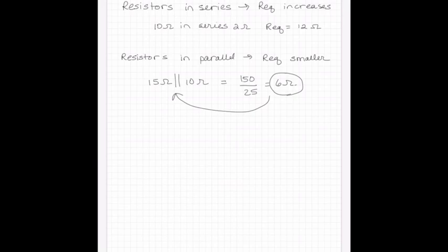We talked about that a little bit in another lecture. When you combine elements in parallel, ask yourself if your final answer makes sense. So we've got 10 in parallel with 15, and I got 6. If I got 60 here, let's say for example, I know that right then I've got a problem. I need to go back and figure out what I did wrong. It's most likely a math error, but make sure that you are asking yourselves if your answers make sense.